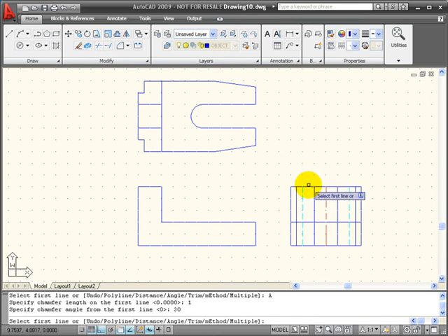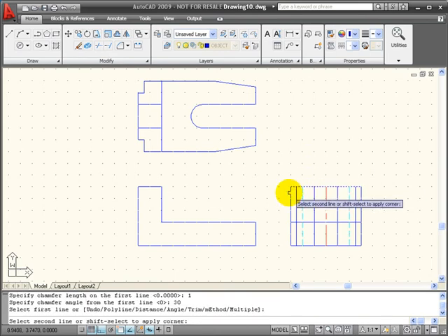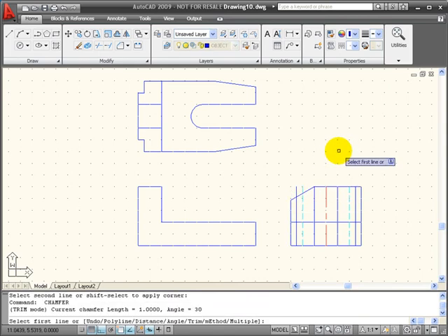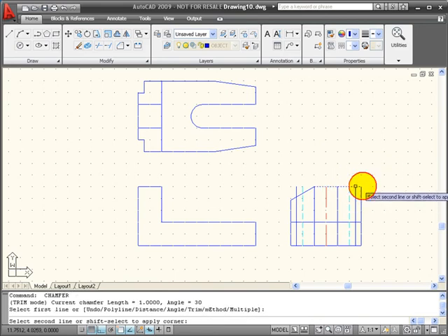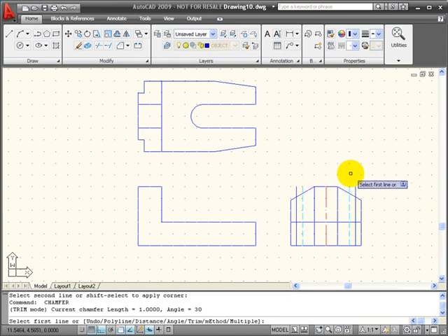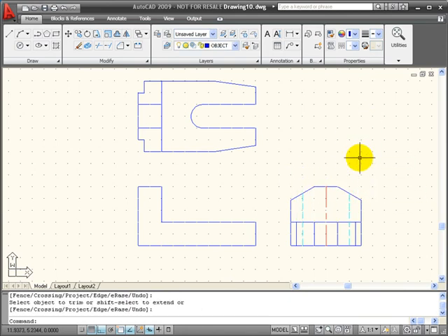This is the line that has the distance. Click. This is the line for the projected angle. I'll hit enter to bring it back and click on distance and angle, and then trim off my excess lines. So also trimming off any of these hidden in object lines that I wouldn't see in this view.